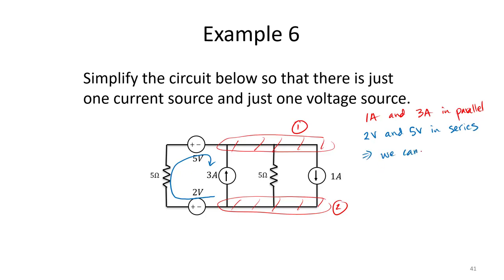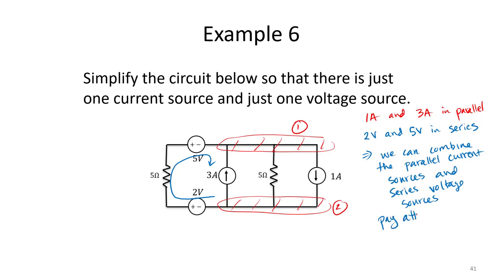Therefore, we can combine the parallel current sources and series voltage sources. Just be careful to pay attention to direction and polarity.